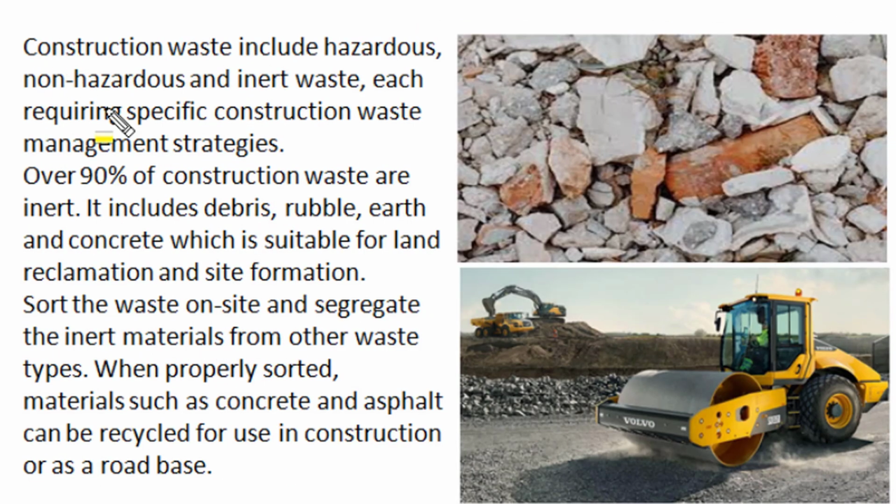The construction waste includes hazardous waste, non-hazardous waste, and inert waste. And all three, inert, non-hazardous, and hazardous waste, require specific waste management strategies. Over 90% of waste generated in any construction site is inert waste, and that includes debris, rubble, earth, and concrete. And such inert construction waste is ideally suitable for land reclamation and site formation.